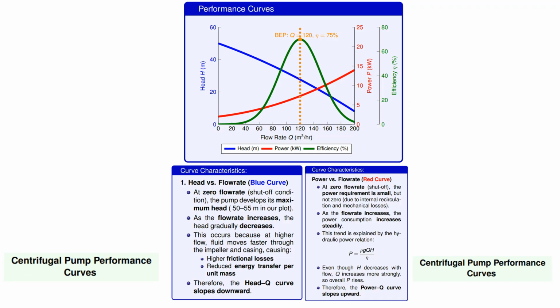Now the power curve in red behaves quite differently. At zero flow rate, the power requirement is relatively small but not zero, due to internal circulation and mechanical losses. As flow rate increases, power consumption increases steadily.